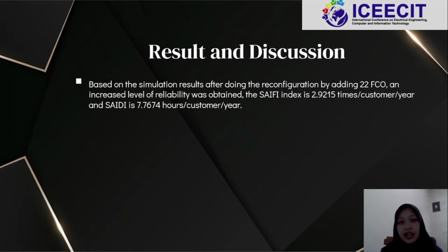Based on the simulation result after doing the reconfiguration by adding 22 fuse cutouts, an increased level of reliability was obtained. The SAIFI index is 2.9215 times per customer per year, and SAIDI is 7.7674 hours per customer per year.